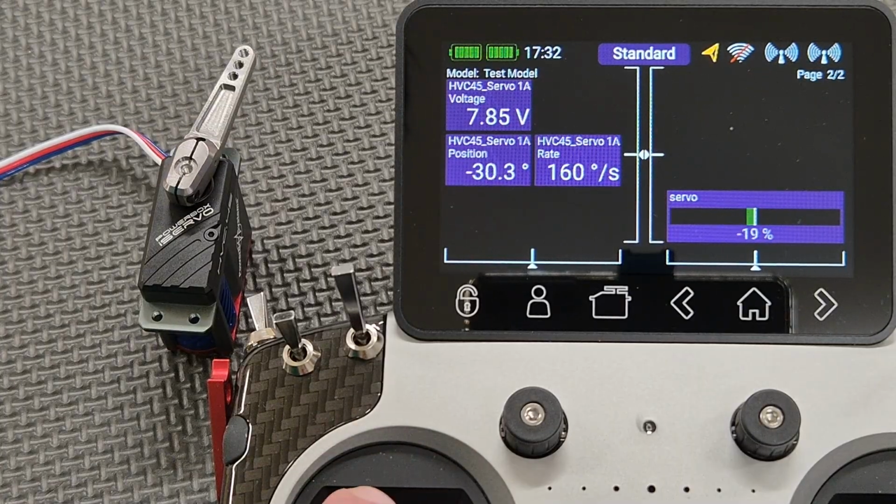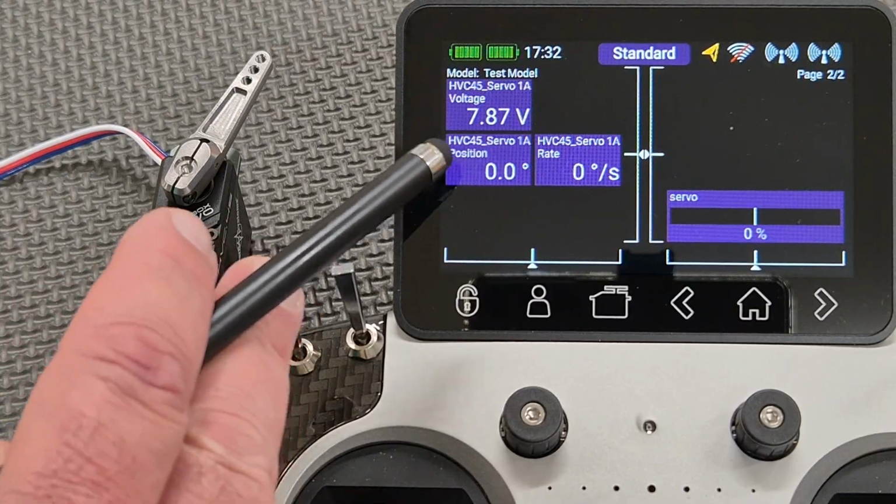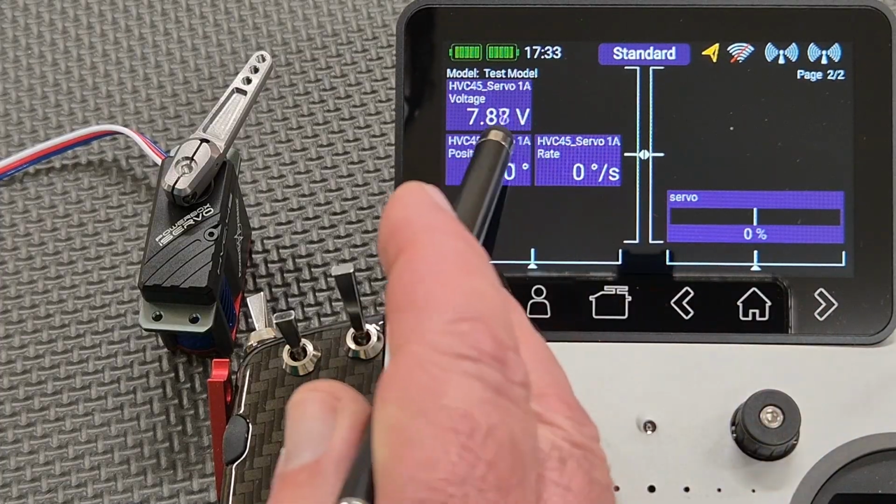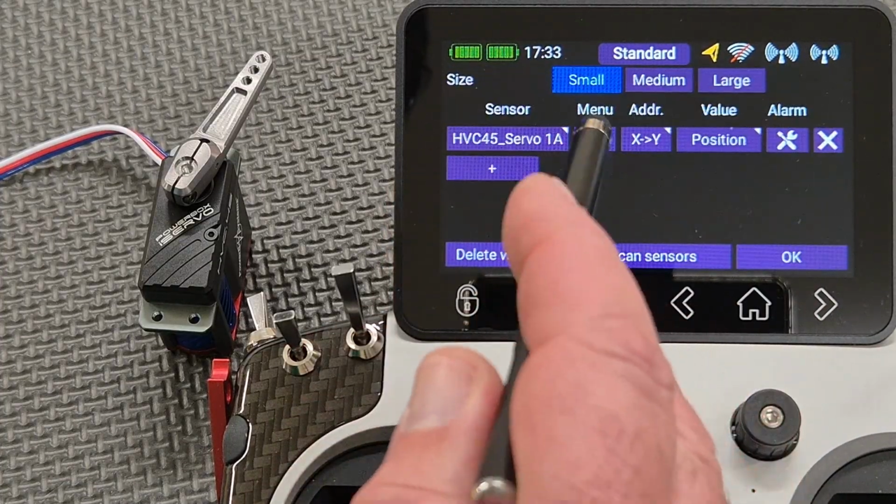Fairly simple, self-explanatory. And you'll also notice that in the widgets, the position widget is set to 0 degrees. So that's offset as well. So everything reads correctly. That's our new neutral position. Again, really handy for aligning servo arms up to their control rods or whatever you're using to move, whether it's a rod or an arm or another arm. You can set perfect 90-degree action where required, or 45, depends on what you're setting up. Okay, let's go back now.